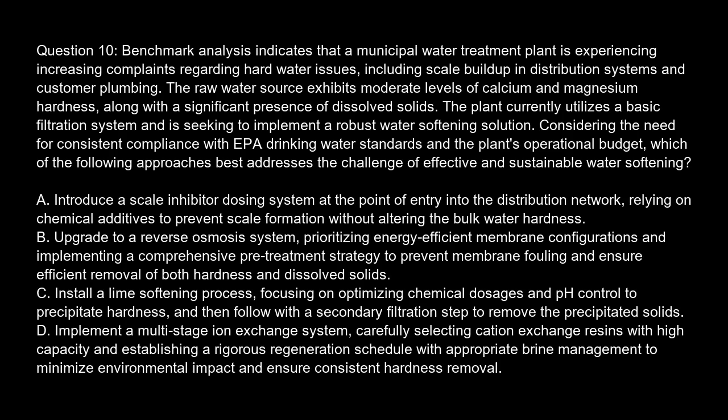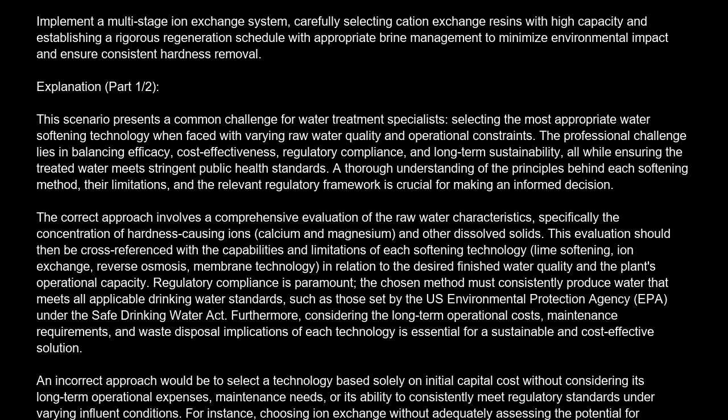Option D. Implement a multi-stage ion exchange system, carefully selecting cation exchange resins with high capacity and establishing a rigorous regeneration schedule with appropriate brine management to minimize environmental impact and ensure consistent hardness removal. The correct answer is D. Implement a multi-stage ion exchange system, carefully selecting cation exchange resins with high capacity and establishing a rigorous regeneration schedule with appropriate brine management to minimize environmental impact and ensure consistent hardness removal.